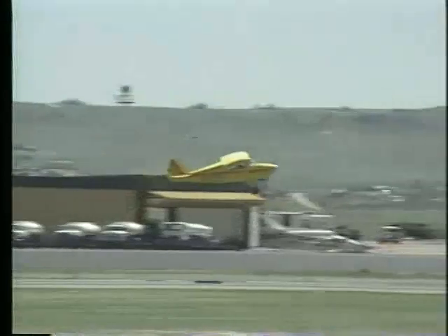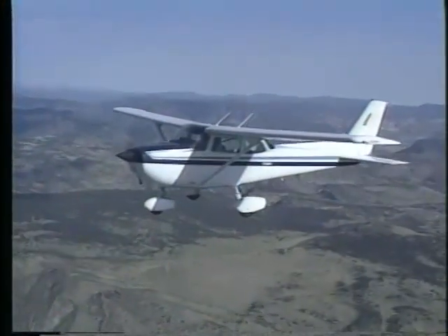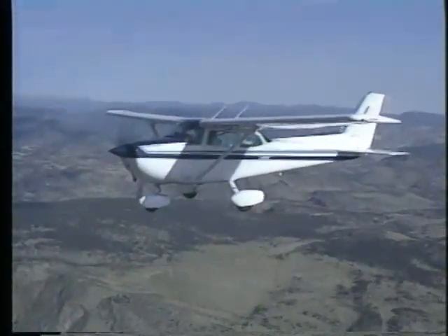The overall angle of the blade determines its operating efficiency in various phases of flight. A propeller with a low blade angle is capable of producing more RPMs and is best suited for takeoffs and climbs. A blade with a high angle, however, is more efficient for cruise flight.